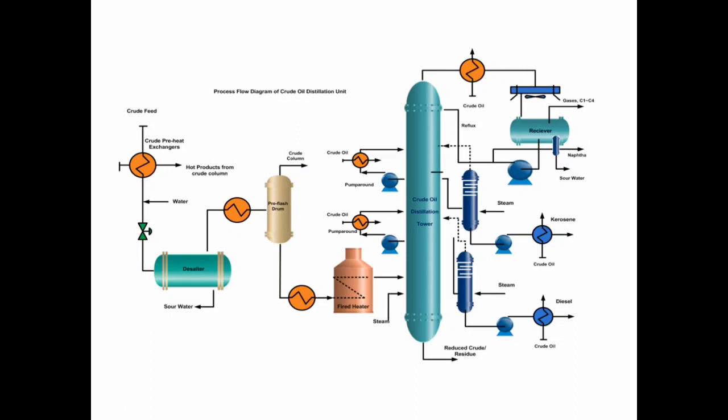Where from the bottom is the stabilized naphtha, if we want to further separate, then it is again taken to the deethanizer, from the top the fuel gas is extracted, from the bottom the LPG. Again, these are pumped, and again it is heated, and afterward again some amount of lighter fuels are taken.